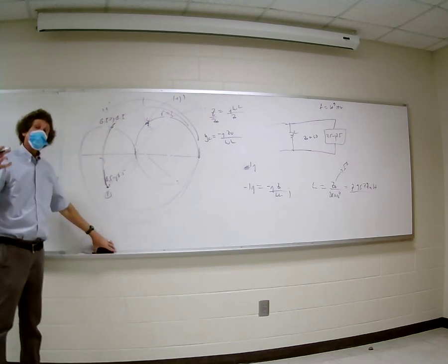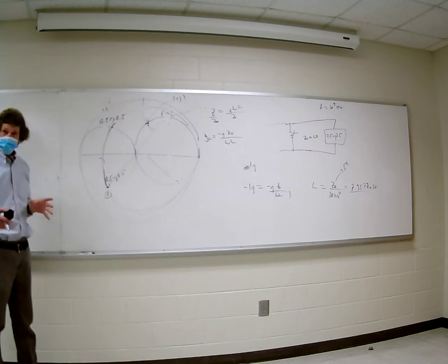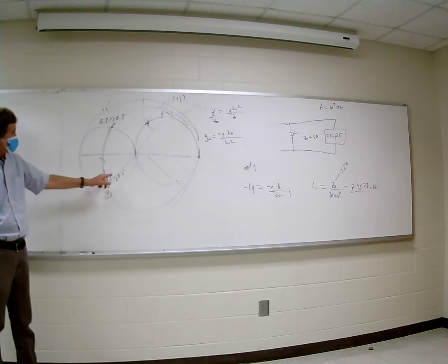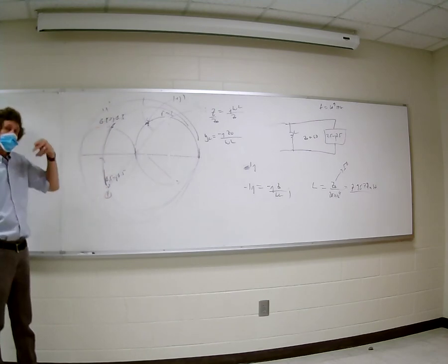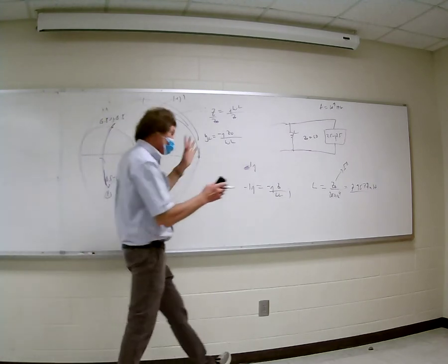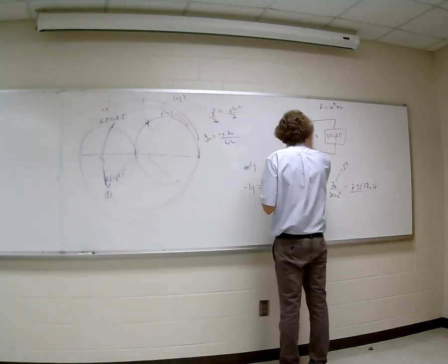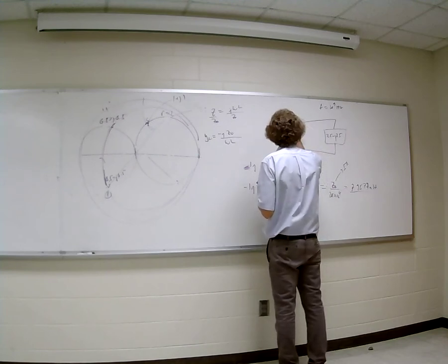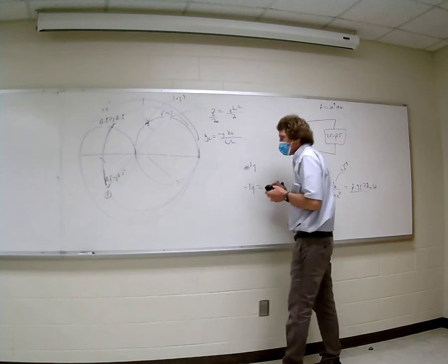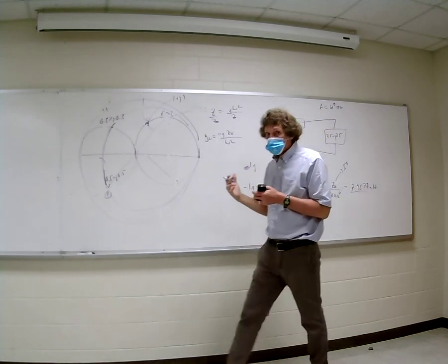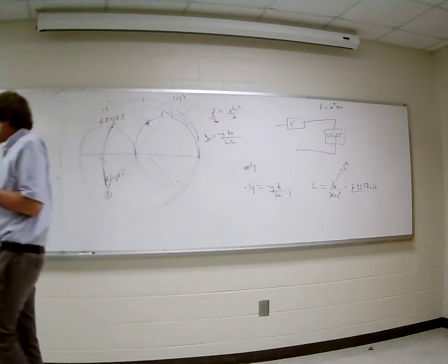All right, now that's adding an impedance, right? It's normalized. How much impedance do we have? This would be a series element. Impedances are always in series. I went from minus 0.5 to plus 0.5. I added 1, didn't I? So that means what I'm going to do, forget this design. This design, it'll work, but it's not going to work for every situation. What I'm going to do is add something here, an impedance that's got a normalized value of J1. That's the normalized impedance, right? That would be an inductor.